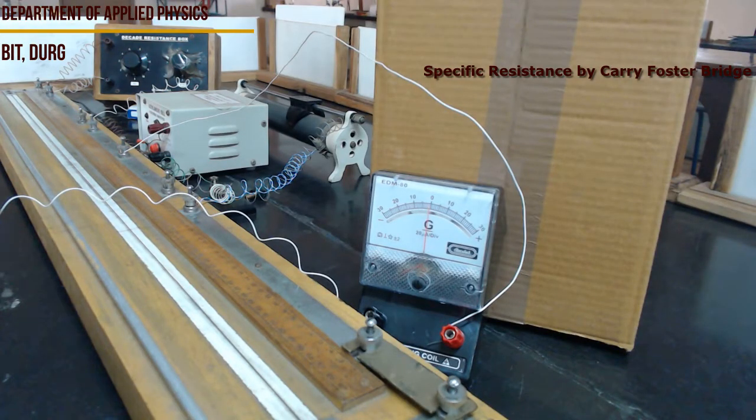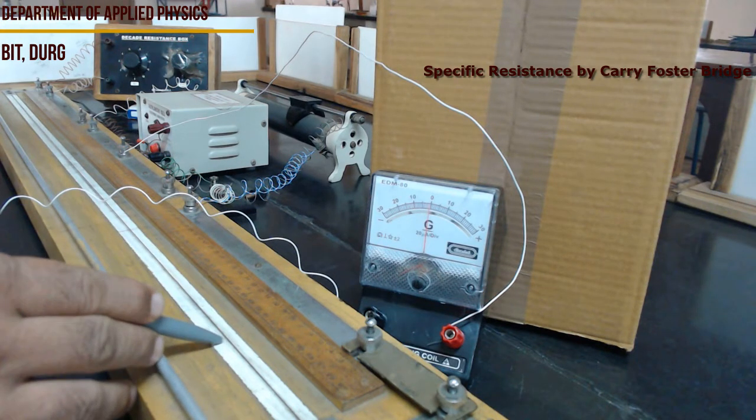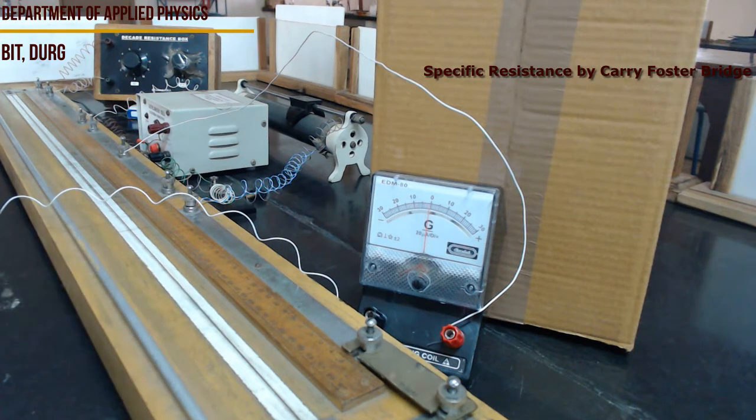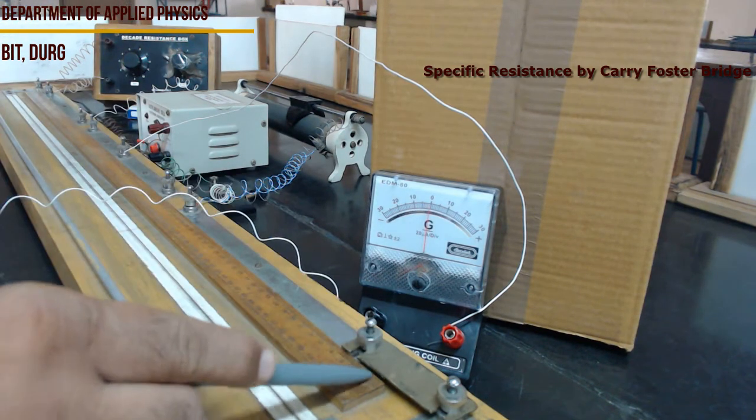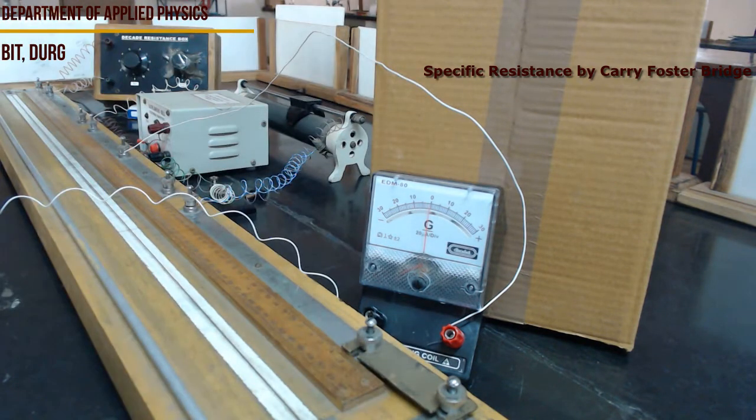So this is the arrangement for first calibrating the potentiometer wire. Means we want to find what is the resistance per unit length of this potentiometer wire. So first we have to calibrate this wire itself, this potentiometer wire. What is the resistance corresponding to 1 unit length of this resistance wire? Then we are going to get the resistance of the experimental wire. And for that, in the left gap there is a resistance box. In the right gap there is a copper strip. As I told you, this copper strip is going to have resistance approximately equal to 0.